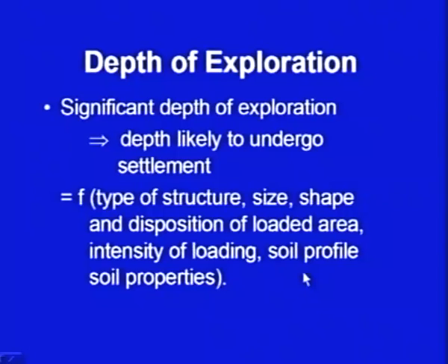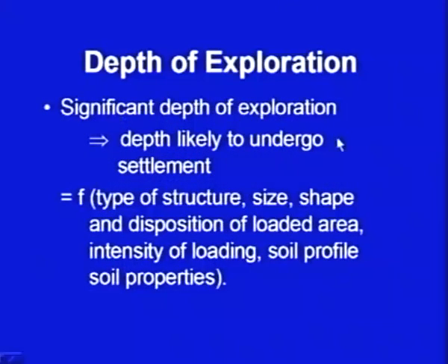Now, let me talk about what should be the depth of exploration. This is the thing which you have to decide when you plan for the detailed investigation. One basic thing to keep in mind is what is called the significant depth of exploration, that depth which is likely to undergo settlement. It means we should know about the strata below the foundation which is causing the settlement, and it should be a function of the type of the structure. It will depend on the size and shape of the footing, the disposition of the loaded area, intensity of loading, soil profile, and soil properties. On all these things, this will depend.